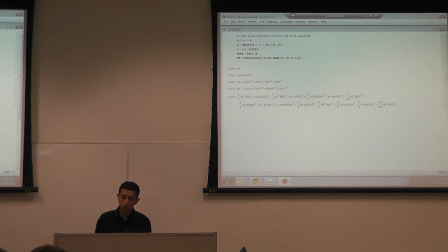The work done by the external forces is integrate the distributed load, which is a constant C, multiplied by X, multiplied by U, when X is 0 to L, minus force P multiplied by displacement when x is L. It's not any displacement, it's a particular displacement. It's the displacement when x is equal to L. Shift enter, you get a huge expression.